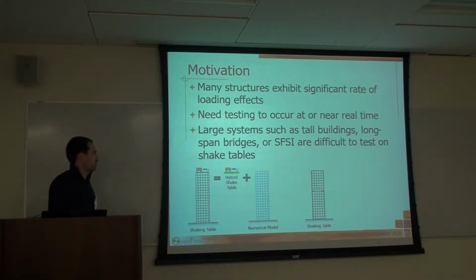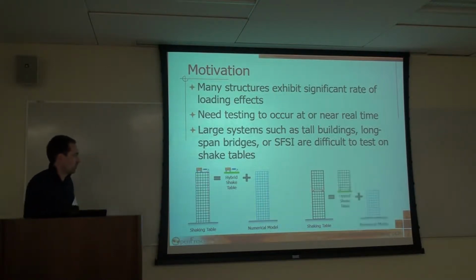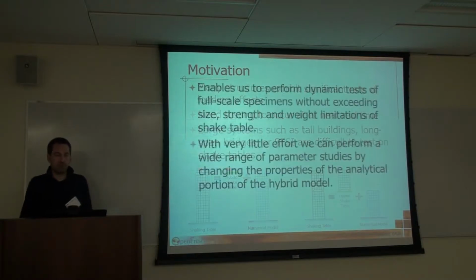Another thing we can do, if we have for example this mid-level isolation system, is the same concept. If we want to do this whole tall building with a mid-level isolation on one shake table, it becomes very tricky to do this in full size, full scale. However, if we break it up, we might be able to actually fit the top portion of the structure that sits on the isolation onto the shake table, and then we numerically simulate the bottom portion. So that's kind of the concept.